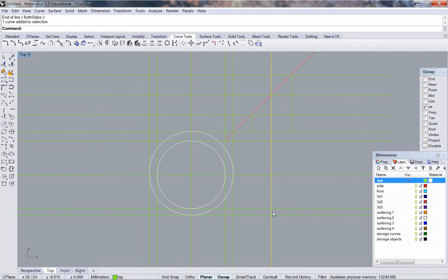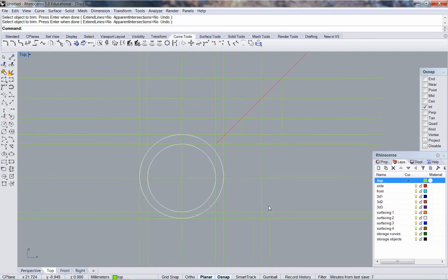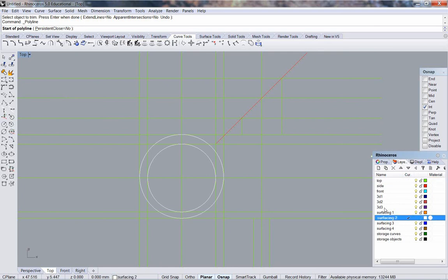width. Our bottommost width we know is 4 millimeters, so we'll offset through point both sides 2 millimeters. Click. To keep it tidy, I'll trim those curves off at the bottom of the ring, and this will allow me to actually draw my side view.